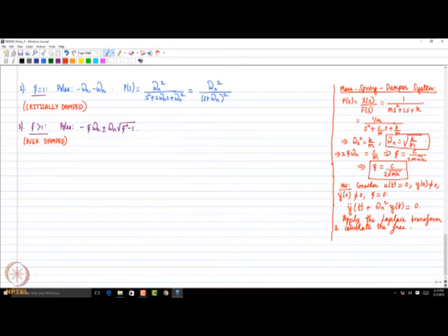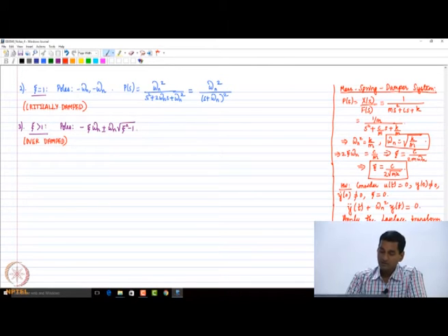You will see that the output term will have sinusoidal terms whose frequency is omega n. So that's the definition of natural frequency. This is something which I want you to do and find out. Is it clear? Okay. So this is the case of the overdamped system, that's when zeta is greater than 1. So please do these things.